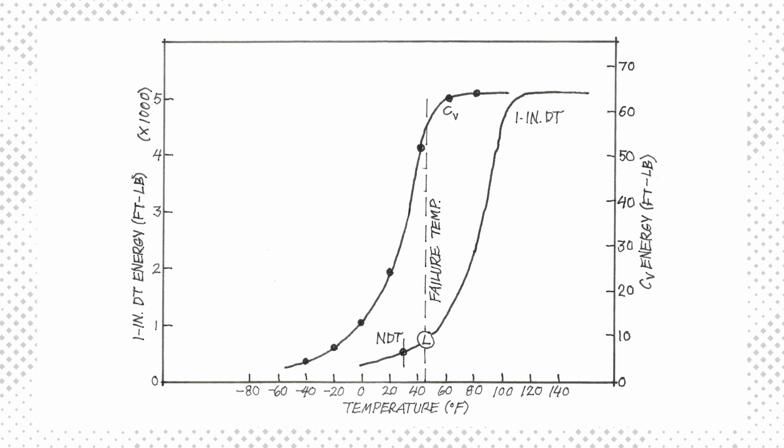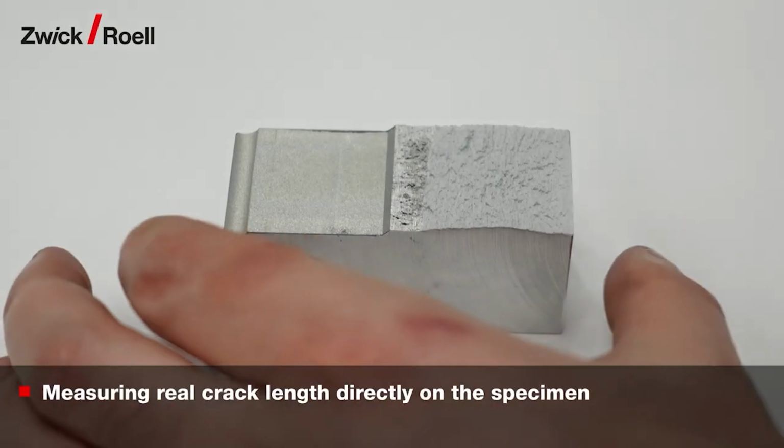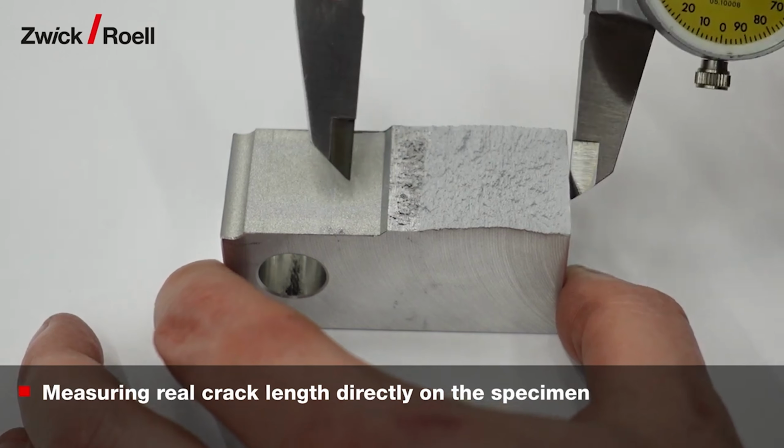Third, test matters. The left curve is from the Charpy test, and the right from a dynamic tear test from a failed structure that surprised many engineers. The design was based on Charpy, which underpredicted the true transition temperature. Specimen type, size, and notch preparation matter tremendously.